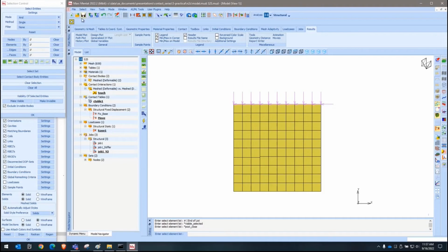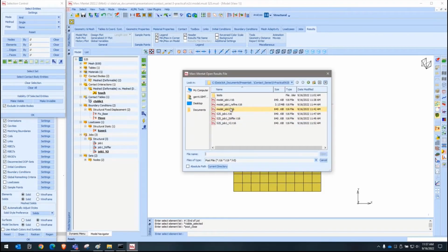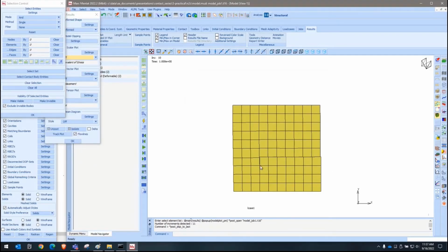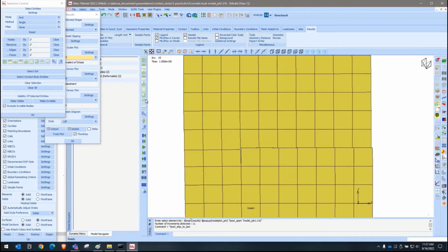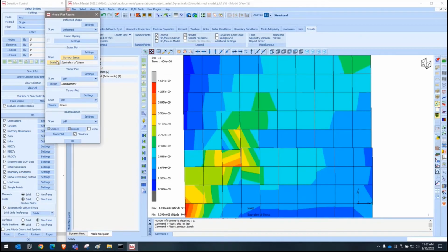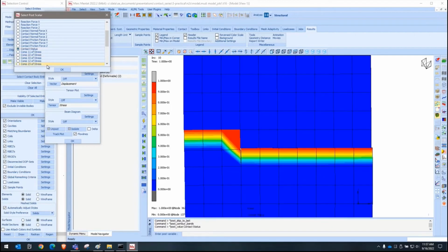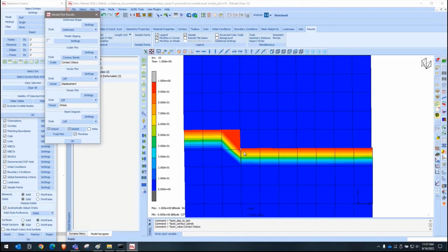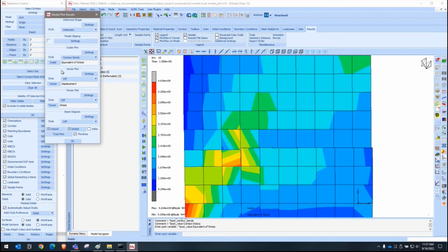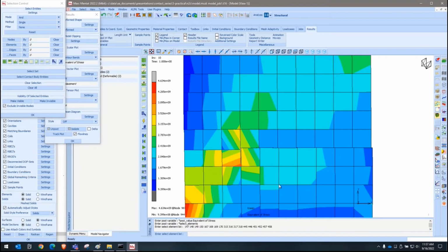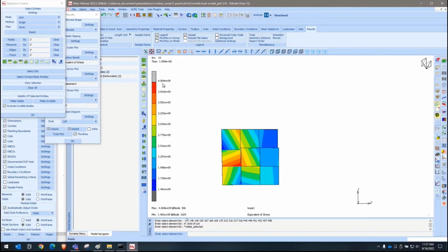Okay, so let's just compare this as well to the original model. So if I look at the first one with the bad contact status, just trying to remember, this is the one I think, let me just double check, this one had the extend edges on. So this is actually probably the closest in terms of accurate. If I look at the stresses of again the elements in just this region, that's very close to what we had with segment to segment with the stiffer properties. The default settings was, I think, 3.8. So there's about 4.1. At least much better than any of the others.